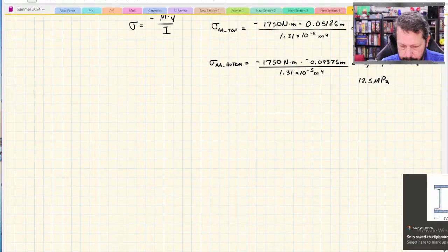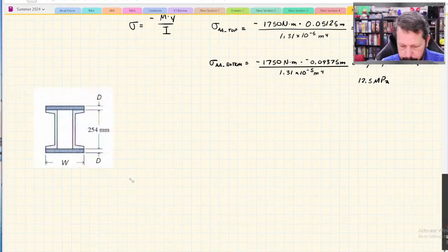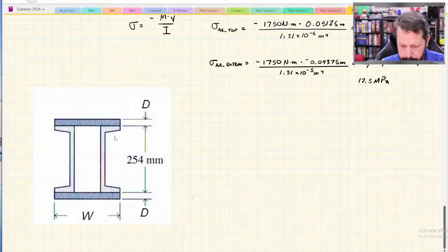So here, this is 2 flat plates, the darker gray, and 2 channel beams, standard channel beams, all welded together into some super I-beam looking thing with a hollow center. Let's see if we can find the moment of inertia of this thing.